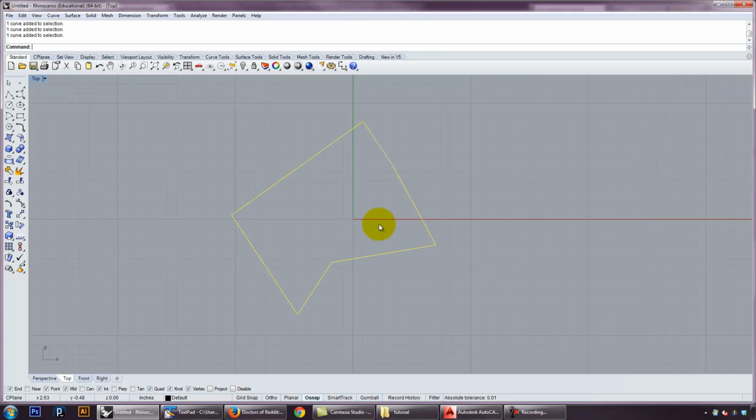So we talked about lines, we talked about snaps. The other things that we have are access to different kinds of primitives. We've got different kinds of ellipses, circles, different kinds of rectangles. If you hold down the mouse button, it'll make all these different commands spill out, similar to AutoCAD. Polygons, including stars, squares, different kinds of things. Polygons are very versatile, so I can change the number of sides that I have in a polygon.